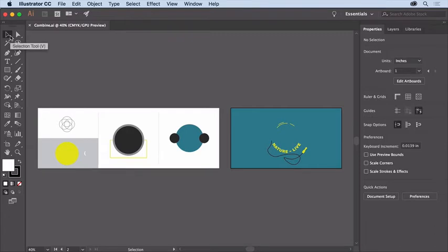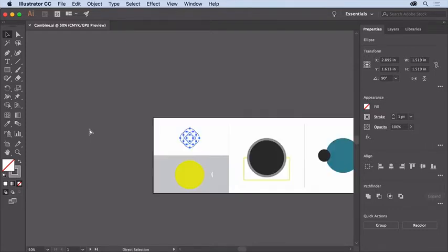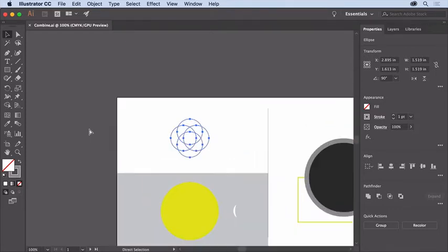With the selection tool selected, drag across the circles here to select them. To zoom in a bit, press Command and plus on Mac OS or Control and plus on Windows a few times. Select the Shape Builder tool in the Tools panel on the left. Now the Shape Builder tool lets you combine or remove shapes you select. So start from off the left side of these shapes and drag through these three shapes to start, then release. You just combined them into one shape.